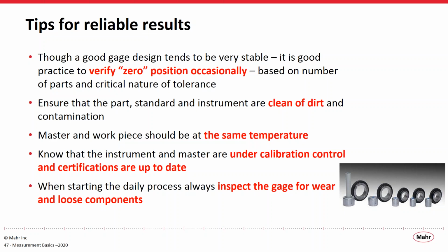It's becoming very critical to document the measuring process. That includes documenting the gauge, documenting the masters, and making sure that the right gauge was used to make the measurement on that part. All those things are starting to be controlled and documented today. And again, every day you should just make it a regular routine to inspect the gauge for wear, loose components, to ensure that we're doing our best to keep the enemy out of our gauging process.